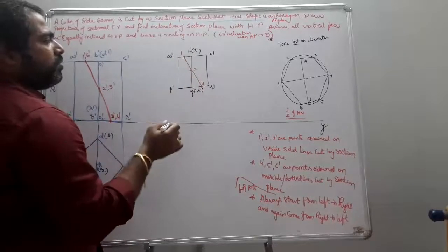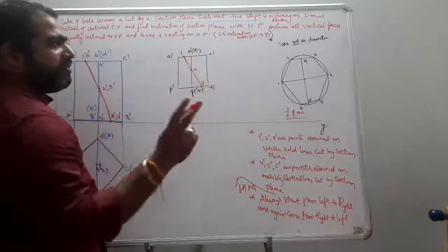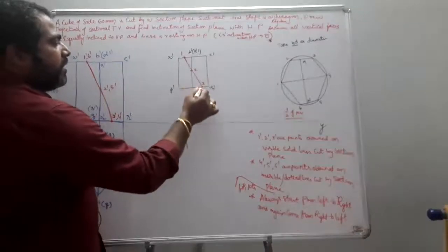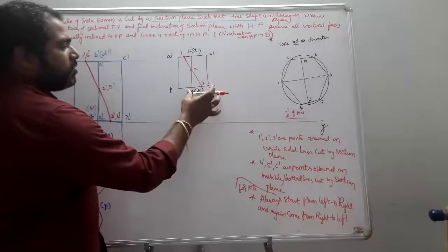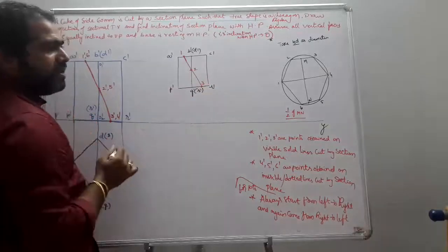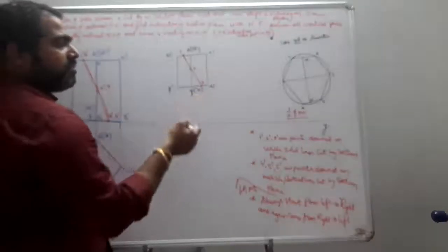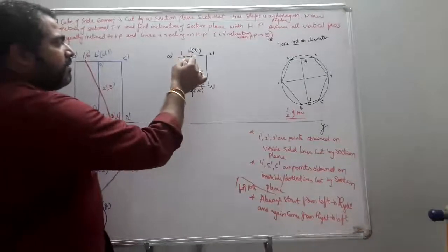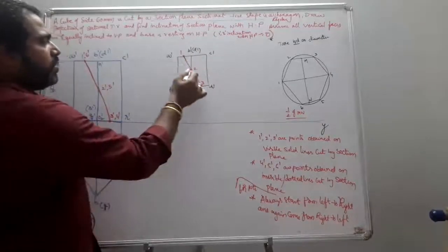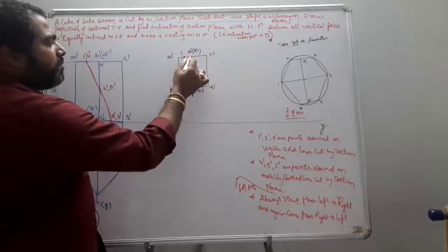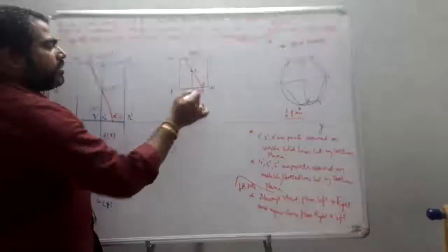So generally we know that whenever your base cuts the base edges, it is going to have 2 points. Why? Because here if it is cut visibly, you are going to see R dash Q dash is the visible edge which is going to be here. RS is the edge which is behind it, which is invisible. So always start giving the points for the solid lines first. Solid line points are completed. 1, 2, 3. A dash B dash solid line, B dash Q dash solid line, Q dash R dash solid line. 1, 2, 3 points are completed.